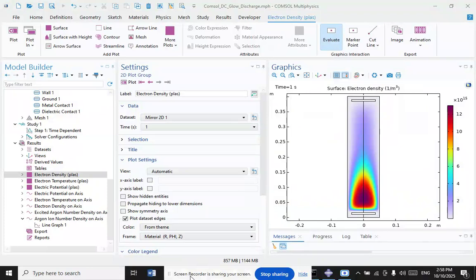Electrons near the cathode are less energetic than the rest of the tube. Surrounding the cathode is a negative field, which slows electrons as they are ejected from the surface. Only those electrons with the highest velocity are able to escape this field, and those without enough kinetic energy are pulled back into the cathode.